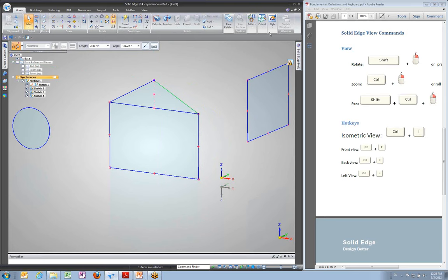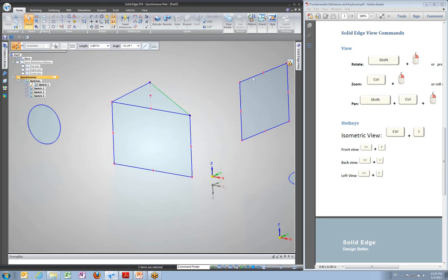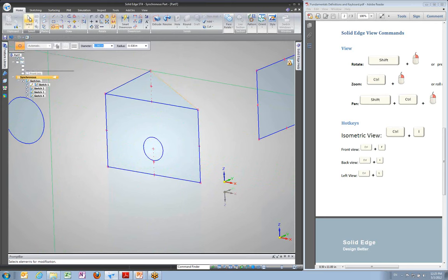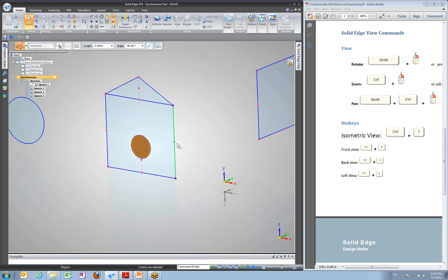Let's place another piece of geometry, again, still locked to that plane. And if you come unlocked for whatever reason, maybe you've clicked on this lock button, just grab any sketch tool and find that plane and hit F3 to lock it. Okay, so now I've got a circle here, and I'm going to draw that circle. I'm just going to come along the bottom here, wait till I see that midpoint, and I haven't clicked to start my circle yet, but you'll see that your cursor kind of wants to stay in line there. And I'm going to click once, drag that cursor out, and notice it's automatically put a horizontal relationship in there. So now, no matter what I grab in here, it'll keep that circle centered on there.